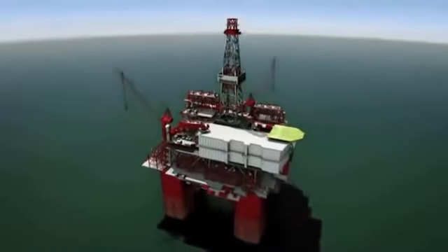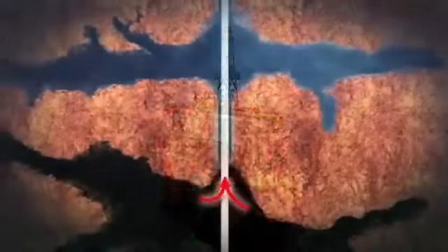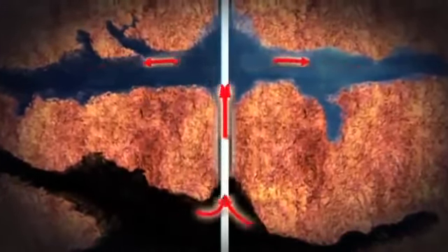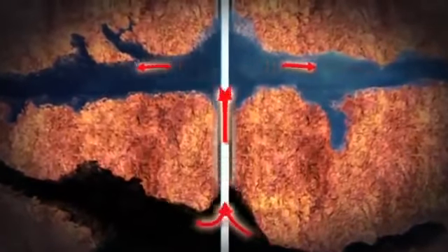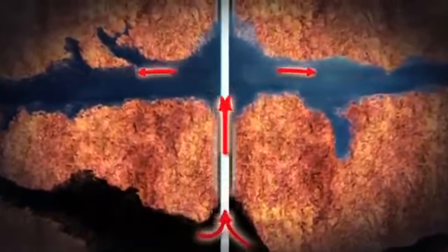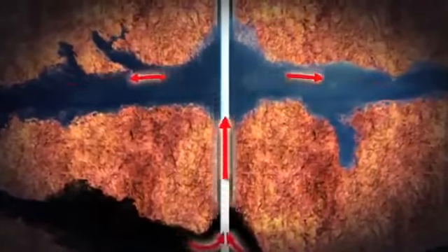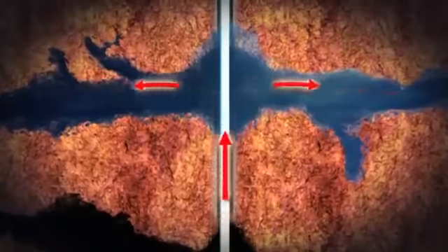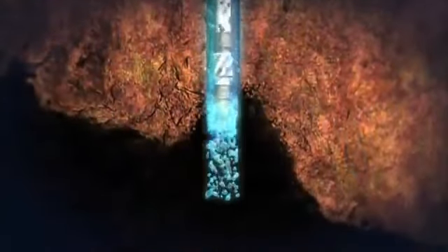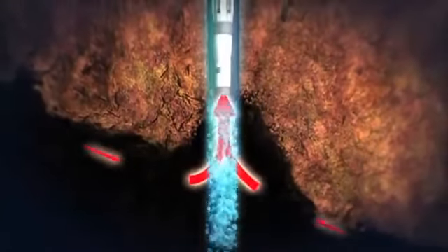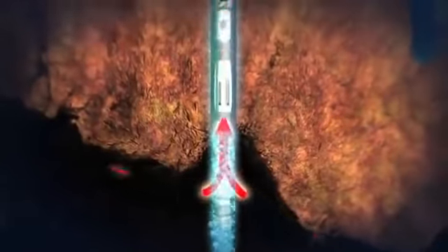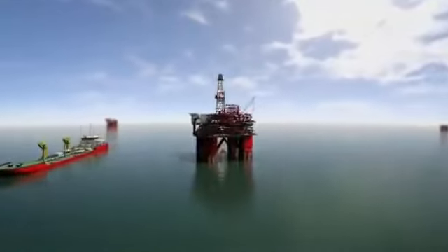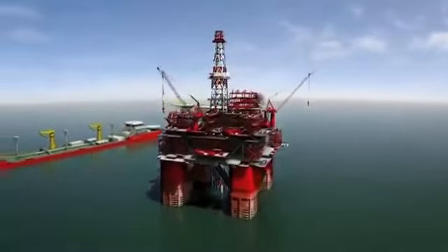Ideal pressurized mudcap drilling well candidates are those where a high or total loss of returns and gas kicks are experienced. These kick loss conditions typically occur in highly fractured or vugular formations where loss rates exceed 120 barrels per hour. But with pressurized mudcap drilling, these losses mean good injectivity, which is an attribute. Wells without these loss characteristics are drilled using another MPD variation, such as constant bottom hole pressure.